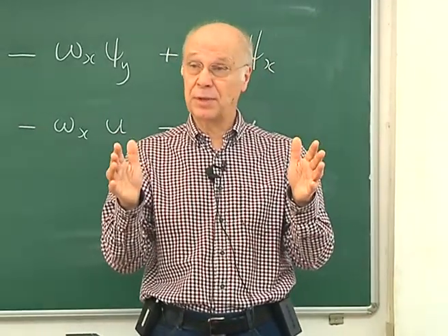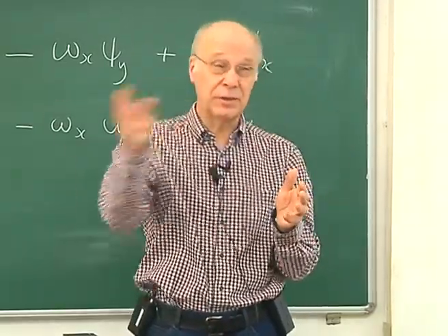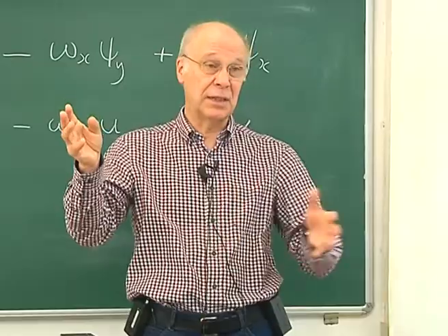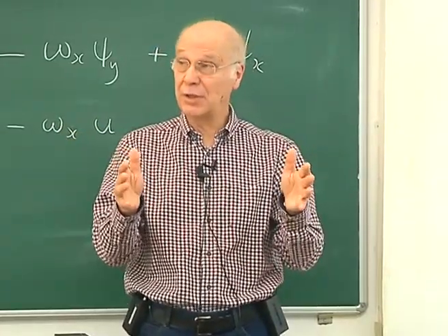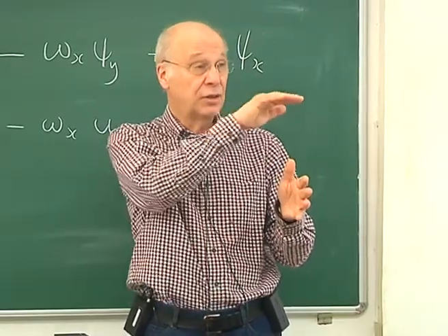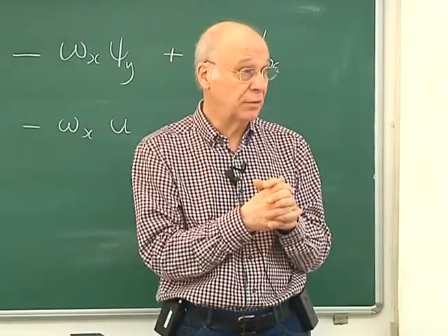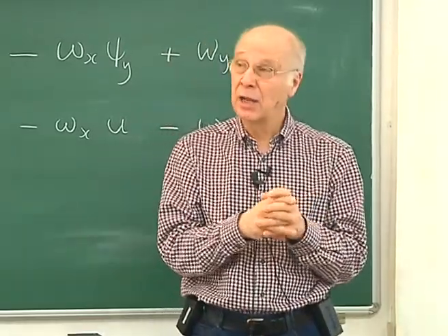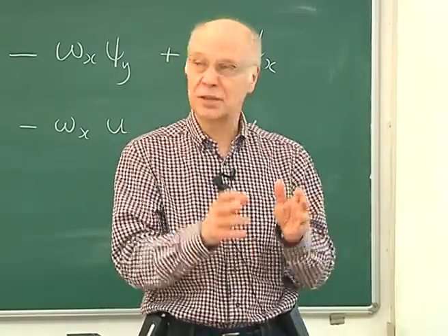In this problem, there is no net momentum in the interior. Agreed, things are moving to the right, but there's a compensating amount moving to the left. So there's no net momentum at the beginning or at the end. And therefore, at all times, it's necessary that the forces added up over all 4 surfaces equals 0. And most numerical schemes will be approximately 0 to second order.